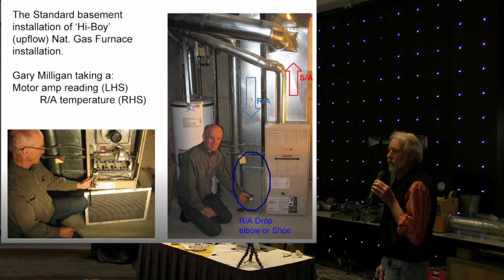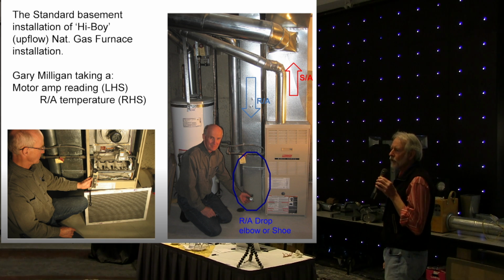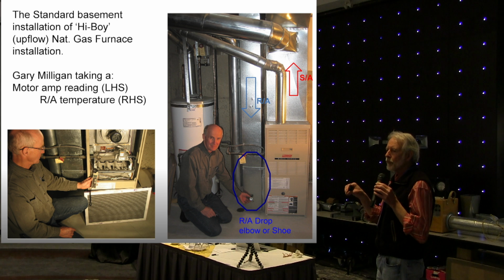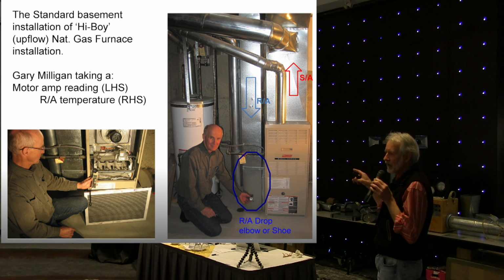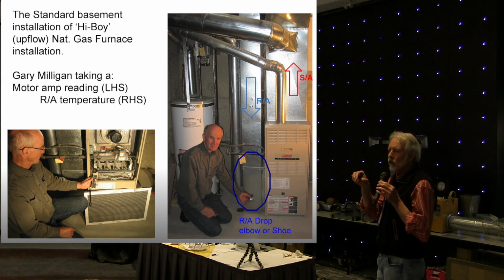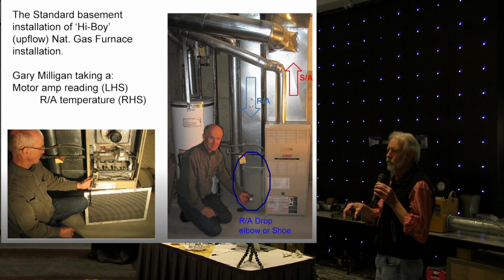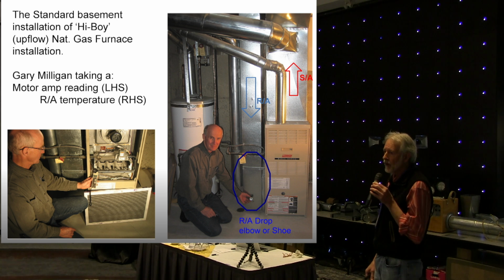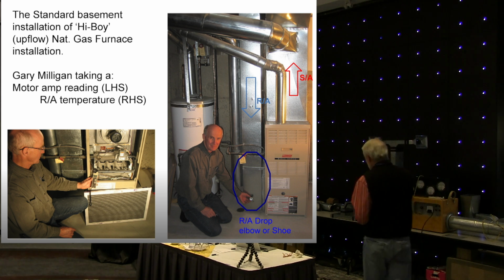Well, Gary Milligan is doing something which every last furnace installation requires that you do, and that is do a temperature rise. It's not being done. But the condition of the approval by CGA of that gas furnace requires the manufacturer in the manual say that the installer shall do a temperature rise and clock the gas meter to make sure that that thing is burning correctly. So, what does he do?